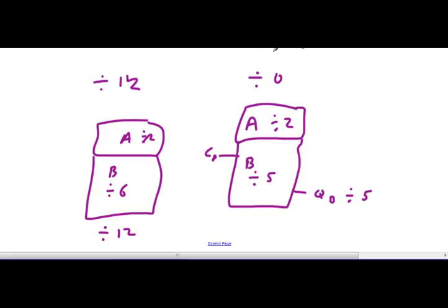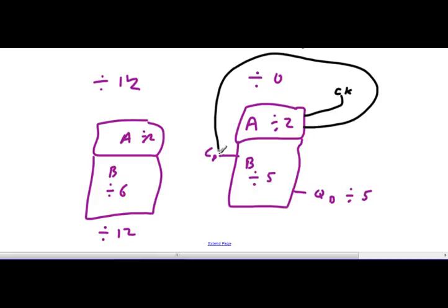If I came in with my clock through the A counter, and then I brought the A counter out, which is now a divide by 2, into the B guy, so that would be QA. Now I have a divide by 10, because I'm using both the divide by 2 and the divide by 5 counter to get the divide by 10.